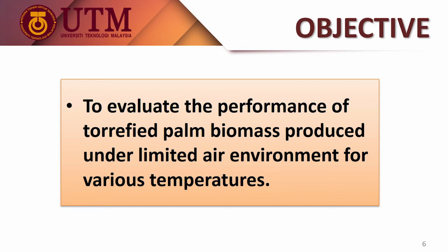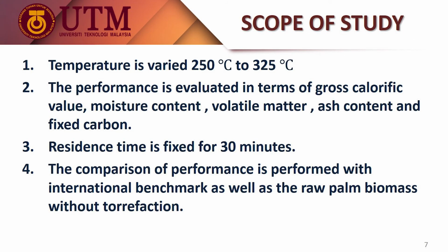So for this study, we want to evaluate the performance of torrefied plant biomass produced by limited air environment for various temperatures. The scope of study is temperature varied from 250 degrees Celsius to 325 degrees Celsius. The performance is evaluated in terms of gross calorific value, moisture content, volatile matter, ash content, and fixed carbon. Besides that, the residence time is fixed at 30 minutes. And the comparison of the performance is performed with an international benchmark as well as the raw plant biomass without torrefaction.